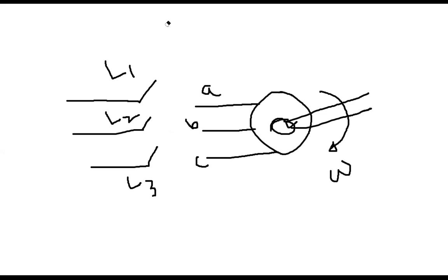And then what you will be doing, you will be just swapping two lines. You will make connection this one here, and this one there, and then this one. The next time if you start the motor, then you will see it is properly rotating in the suggested or given direction. I mean, you just need to interchange any of the two lines. Then that will fix the phase sequence issue, and the motor will properly rotate in the suggested direction. So everybody, could you follow me on the importance of the phase sequence?